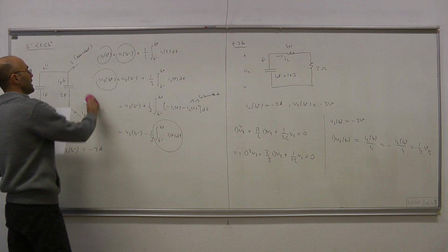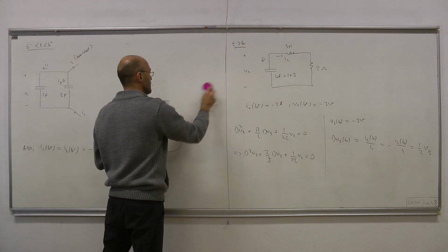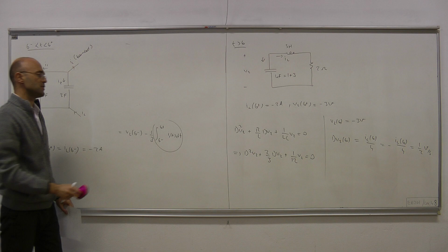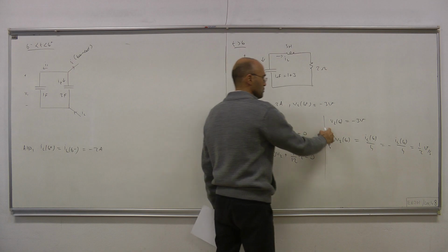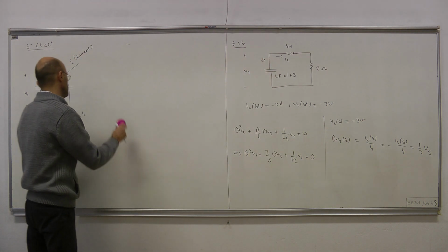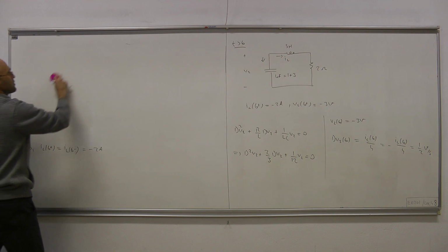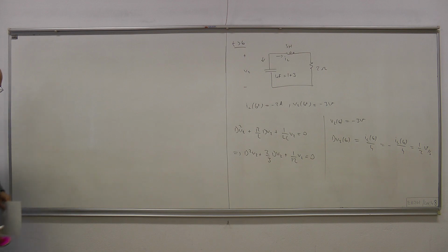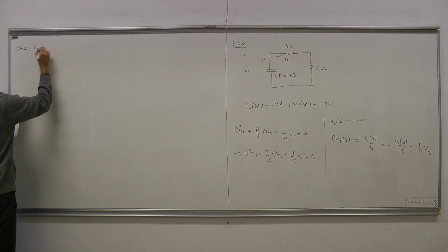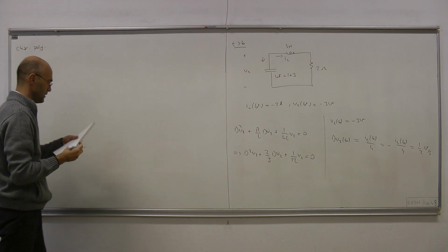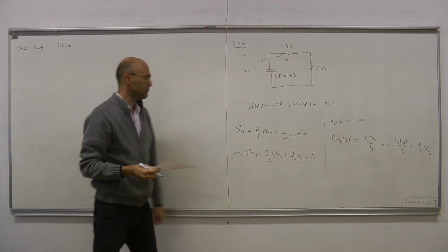Okay. Now, by looking at the differential equation, we gather the characteristic polynomial from which we obtain natural frequencies, and those natural frequencies will tell us the homogeneous solution. And by applying the initial condition constraints to the homogeneous solution, we figure out the response. So the characteristic polynomial for this circuit is, look at the differential equation, pick the coefficients.